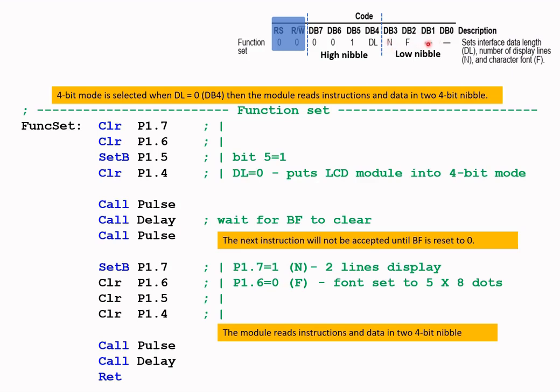these parameters here. So let's focus on the last 4 bits, because that's the 4-bit mode operation. Again, we'll cover this up here. So the high nibble: because this is a function set, DB5 has to be set to 1. So DB5 will be set to 1, and the other 3 parameters are DL, N, and F. First of all, let's take care of DL.